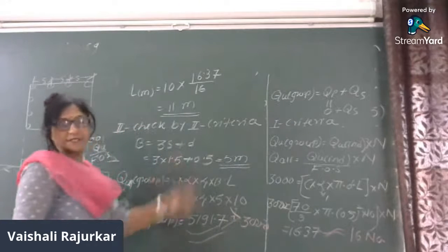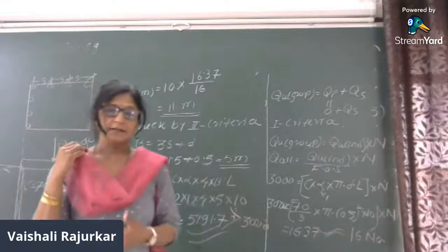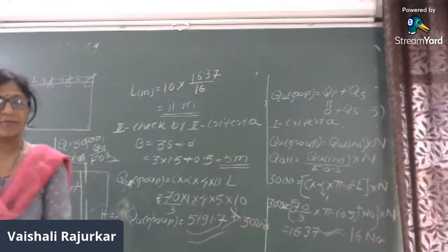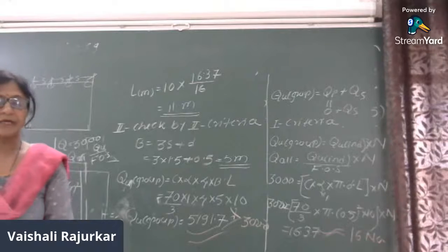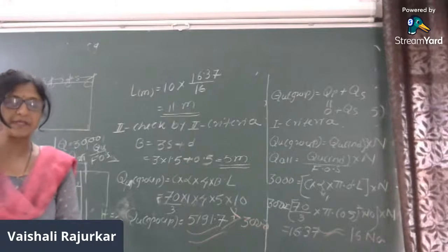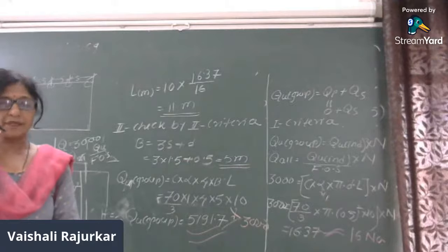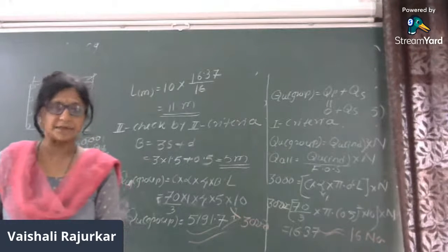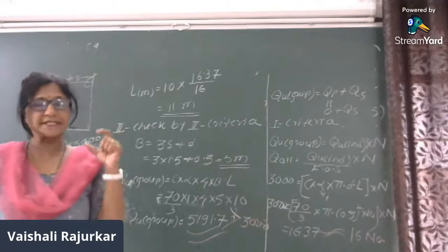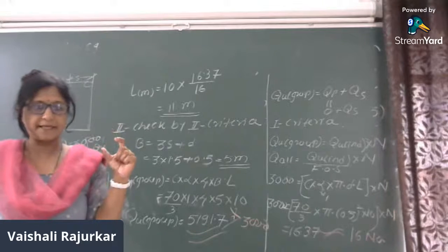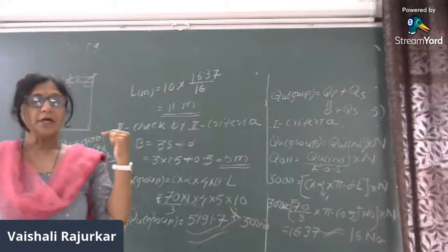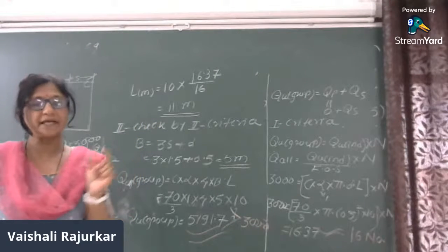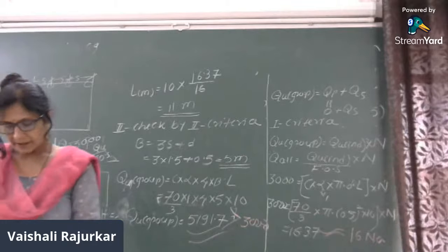So whatever assumptions we have made, those are the safe ones. Therefore, whatever assumptions we have made, they are correct, and then we can go with these given parameters where there are 16 piles of diameter 0.5 and length is 11 meter. Previously we had considered 10 meter as the length, but when the number of piles came to more than 16, we rounded it down to the lower side, and therefore we have modified the pile length.